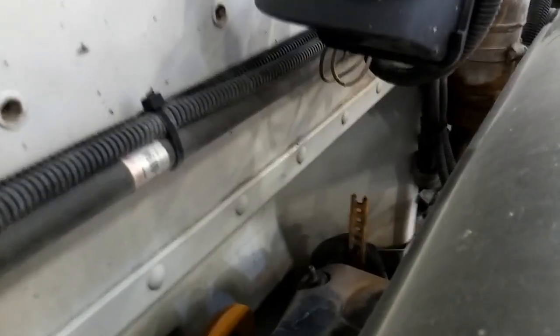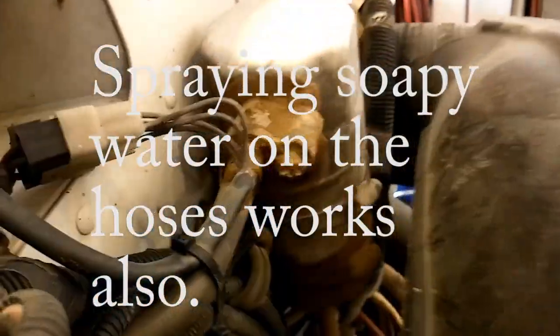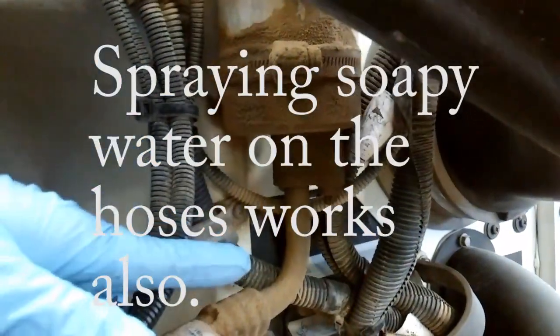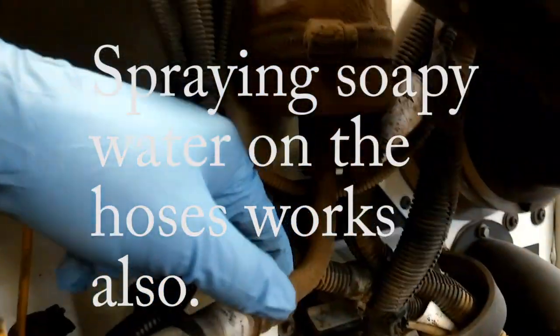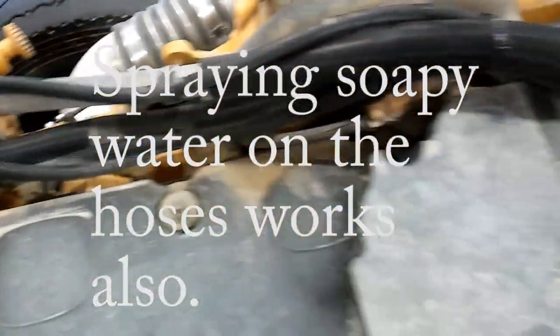So if you've seen the second video, you already know where it's going to be, but look at that. Your accumulator here has some nasty oily dirt buildup around the fittings mostly, which means probably the O-rings are bad or the hoses. This hose here is pretty much caked with dirt along that fitting area. So I went ahead and replaced that hose and the O-rings going to it, and also the O-rings going into the accumulator.